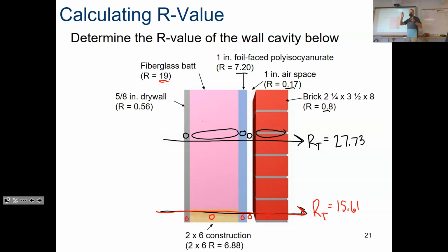In every wall, heat can travel through the different parts of the wall faster or slower. If you were to look at a wall with a thermal camera, you can actually see where heat is leaving through the studs. You can see studs in a wall just by looking at them with a thermal camera when it gets cold outside. You don't need a stud finder. You can get a picture of where every piece of wood is, because this is called a thermal bridge. Heat can travel across the bridge and go to the atmosphere through the wall.